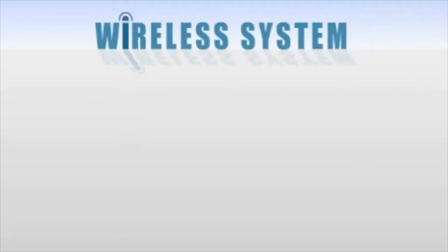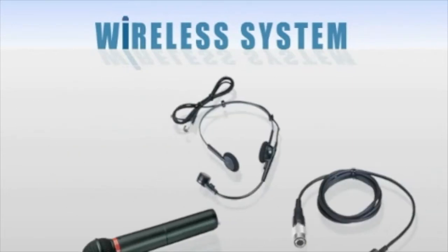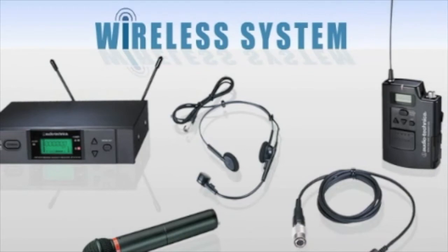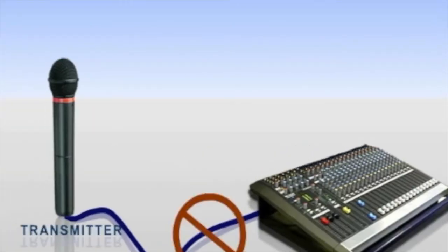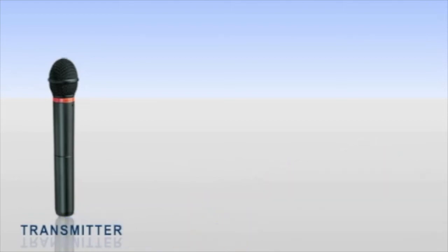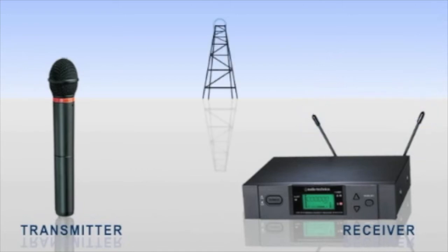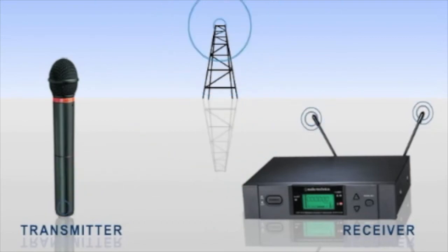Wireless microphone systems have become highly sophisticated systems capable of delivering the same performance and reliability of wired microphones and providing increased mobility. The basic fundamental purpose of the transmitter and receiver is to provide freedom from a microphone cable. The trade-off is the fairly narrow band of radio frequencies available for transmitting the audio signal to the receiver without interference, and the need of a battery to power the transmitter.